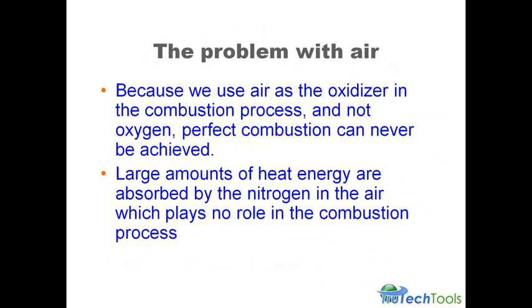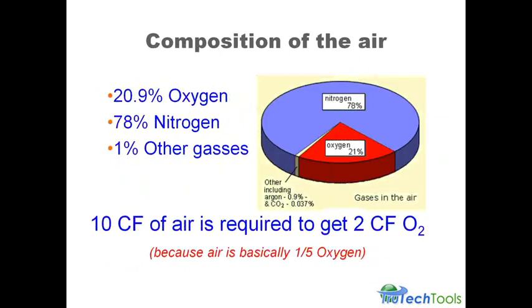And because we're not using oxygen like we would with an oxyacetylene torch as the oxidizer, it's just a function of the product design, and so we want to really minimize the amount of excess air going in the combustion process. There are two things we're going to look at, and we'll get to them later: the roles of efficiency and safety. That's our primary concern.